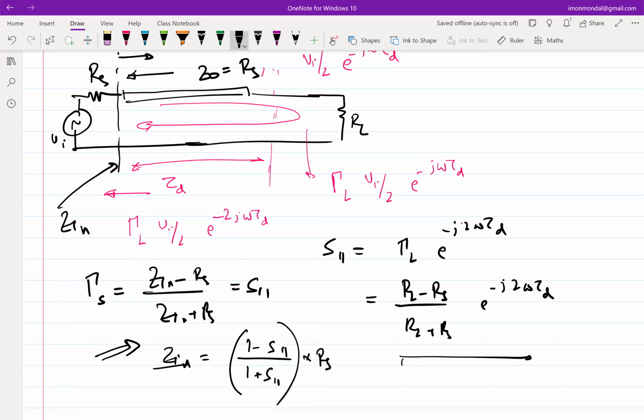Now, this is useful in the case of these instruments because they come with long wires connected to the instrument. You cannot take them out, because when you calibrate, it already knows to some extent the delay of that built-in wire. And if you want to add something to it, your DUT, device under test, need not necessarily be connected just where the wire ends. Some elongated wire can still be there. So you'll have to connect and then run a calibration cycle.